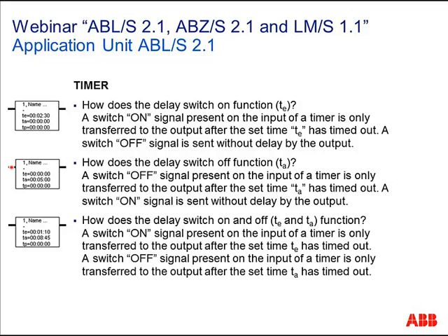On the input, it receives the value 0. Then the off delay time starts, and after 5 minutes it sends this off signal, the value 0, to KNX or to the next element. That's the feature of the off delay. On delay is not available because here I have the 0.